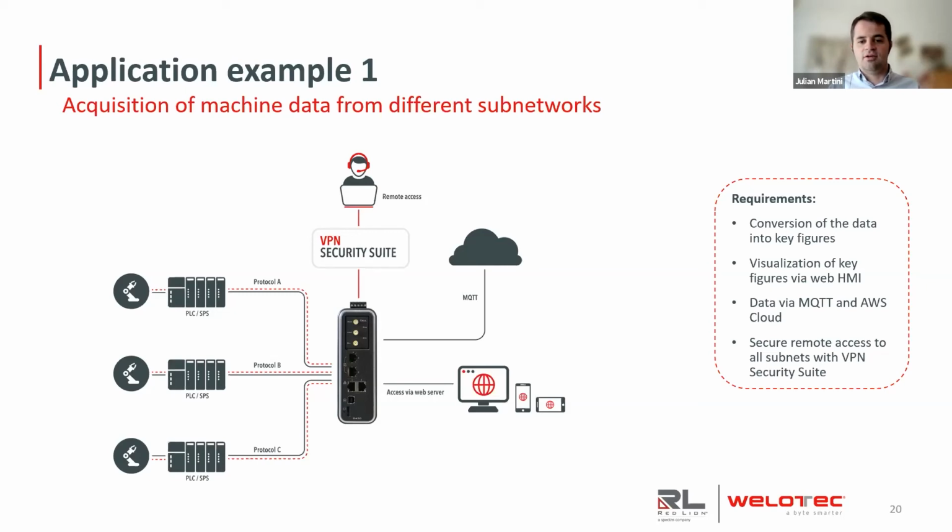So this is a nice all-in-one solution that saves you a lot of money and complexity, because normally to do that kind of setup, you would need at least 3 different protocol converters. So 3 different devices only to convert the protocols. Then you would need an edge computing device to enhance the data and a router. So normally you would easily have 5 devices on the machine level.